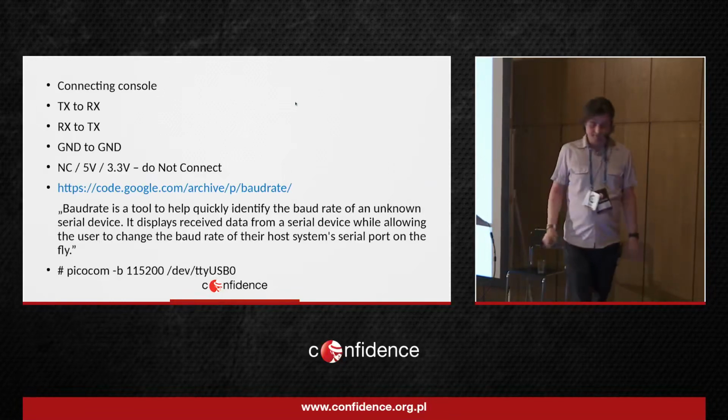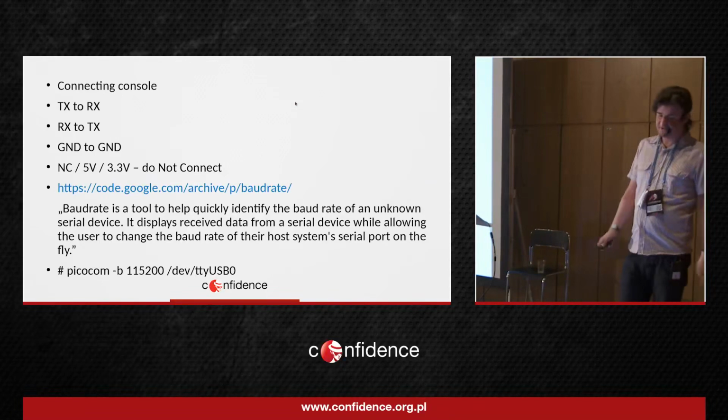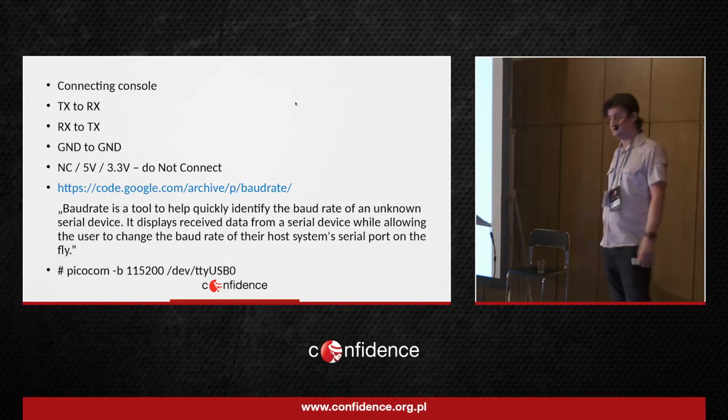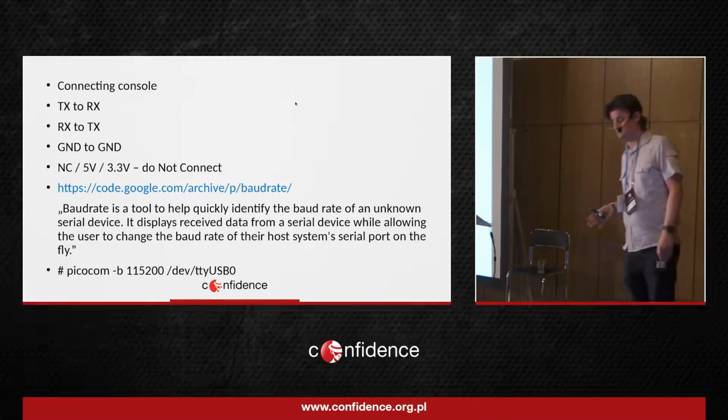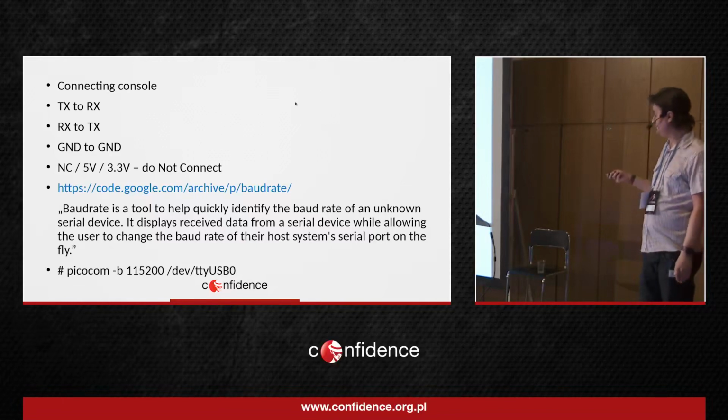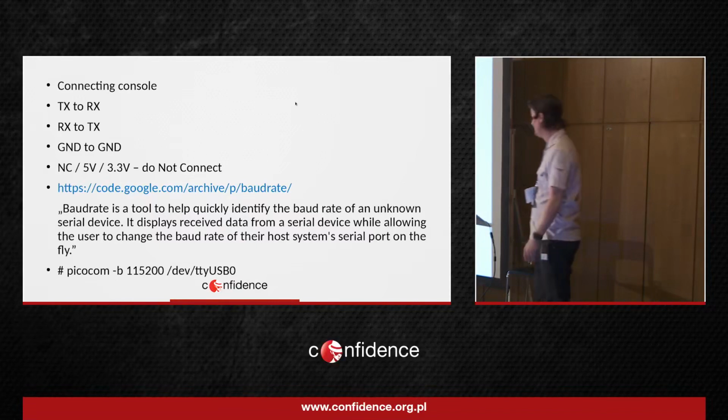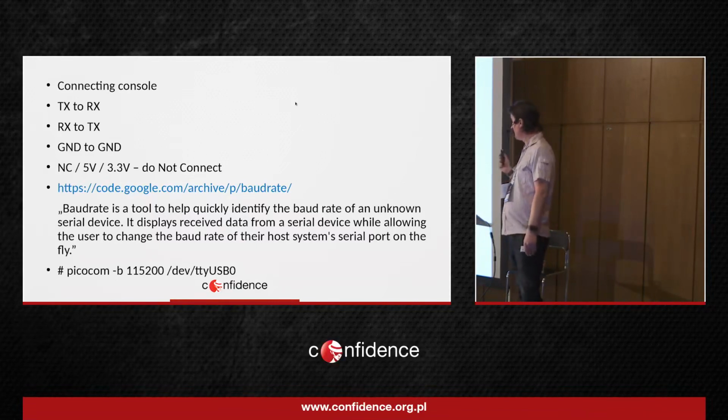How do we connect? This is easy. TX to RX, RX to TX, ground to ground. Never connect power. So NC is no connect. 3 volt, no connect, or you will fry something.